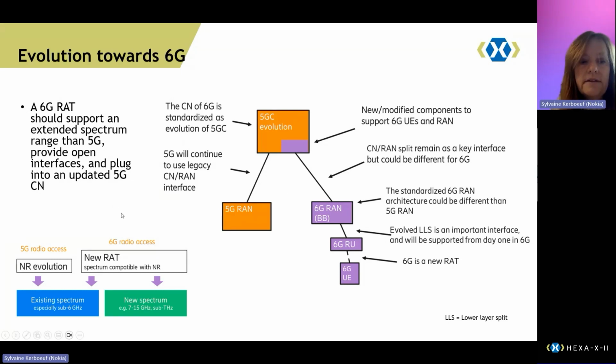Then, looking at the 6G radio access network in more detail, it will indeed be gradually deployed in coexistence with the 5G standalone system. For that, from the first release, we will have multi-RAT spectrum sharing implemented in 6G to allow a dynamic allocation of the spectrum resource between 5G and 6G. This will allow wide area coverage, and then we will also have new centimeter spectrum to provide some boost in performance, and also some higher band spectrum to provide extreme performance.